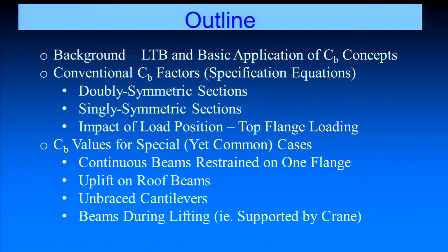Then we'll talk about unbraced cantilevers and another common problem that sometimes we scratch our heads about, which is what do you do with beams during lifting? Usually in the building industry, the beams are relatively light, so it's not that big of a deal. But if you get into the bridge area, those are very long girders and they're relatively heavy. There can be some questions about how you evaluate the stability. Even in industrial applications, you may have lifting beams and so on, and how do you evaluate the stability of some of those structures.